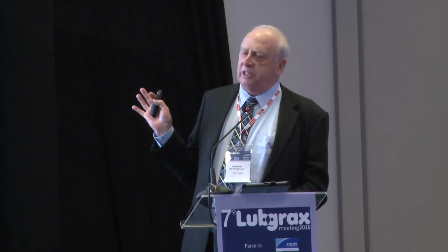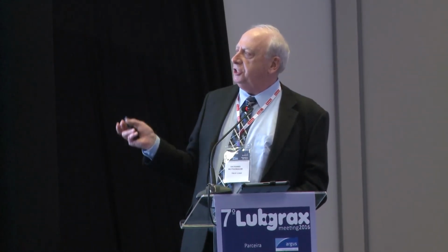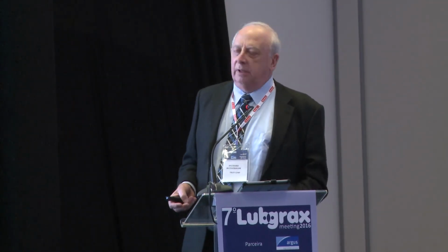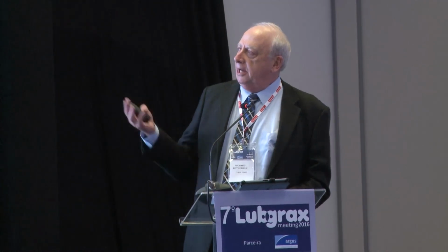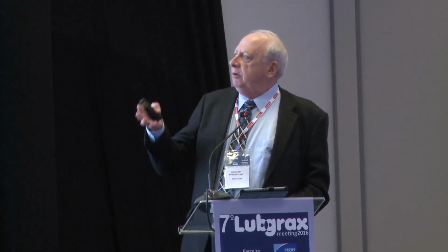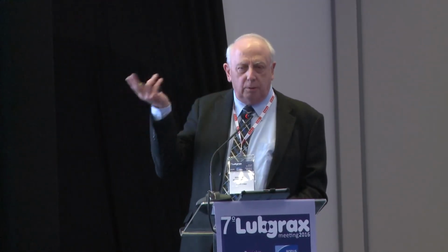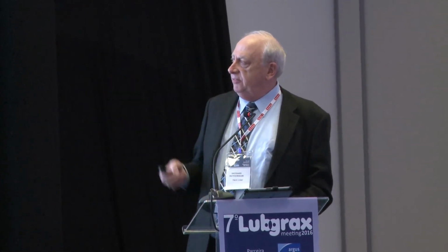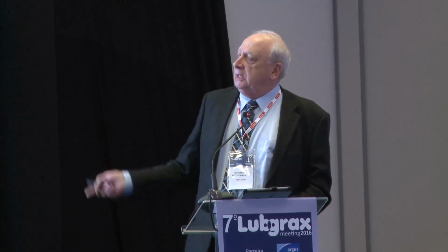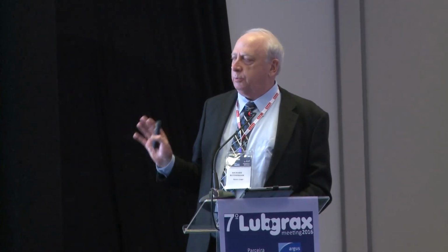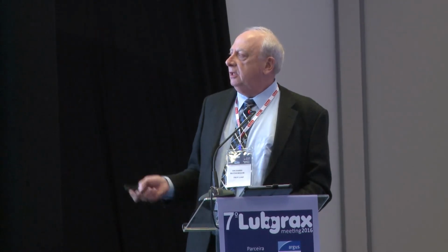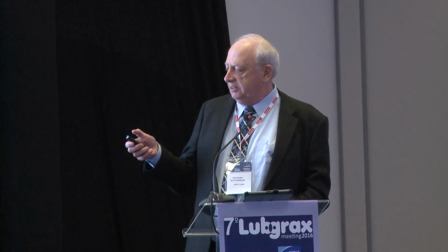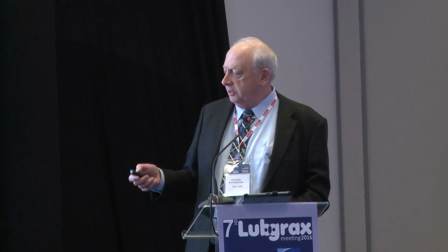Handling with care is always the first order of business, so read and post safety data sheets, and execute a risk management program for handling the product safely. If you know the product is eye corrosive, then where it's being used, there should be appropriate facilities if somebody gets it in the eye. Always wear the recommended personal protective equipment. At the end of the day, the safety data sheet is the primary tool for communicating hazards and saying what to do in case of exposure or to minimize risk.